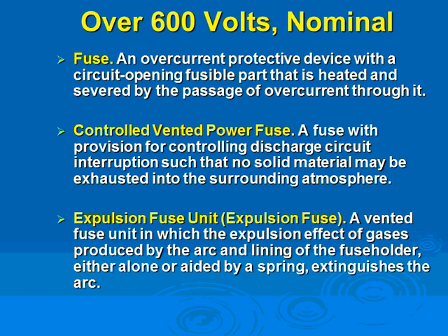Explosion fuse unit. Vented fuse unit in which the explosion effect of gas is produced by the arc and the lining of the fuse holder, either alone or aided by the spring, extinguishes the arc. So they use the effect of the explosion to actually extinguish the arc.